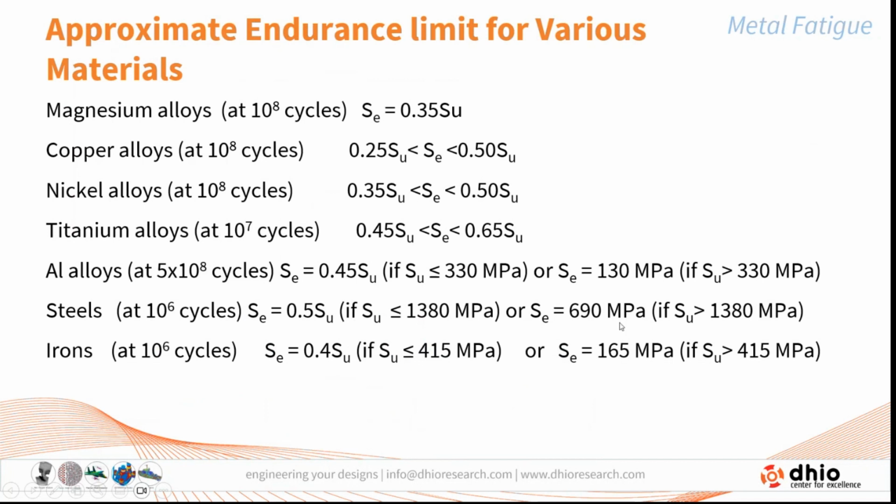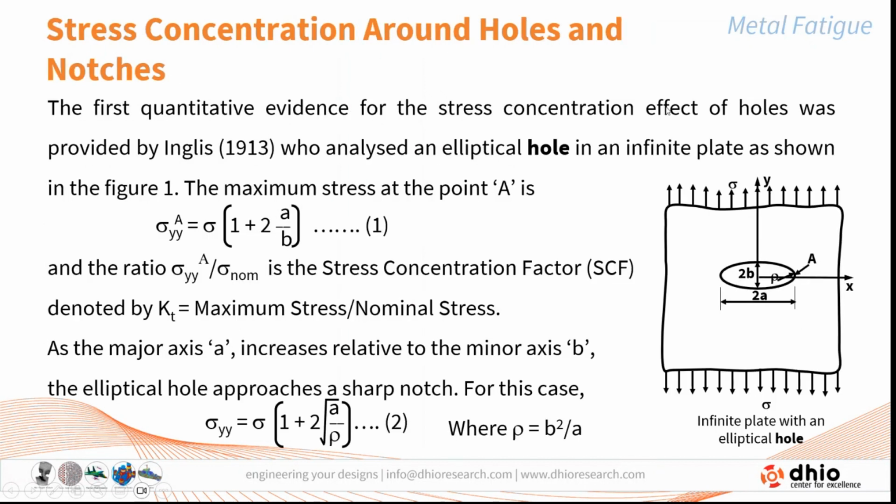Similarly, for other materials, here we have specified to consider the endurance strength of the material. Now, another thing which is going to be key in the stress life approach is the stress concentration. As we all know, the quantitative evidence for stress concentration was first started with Inglis.